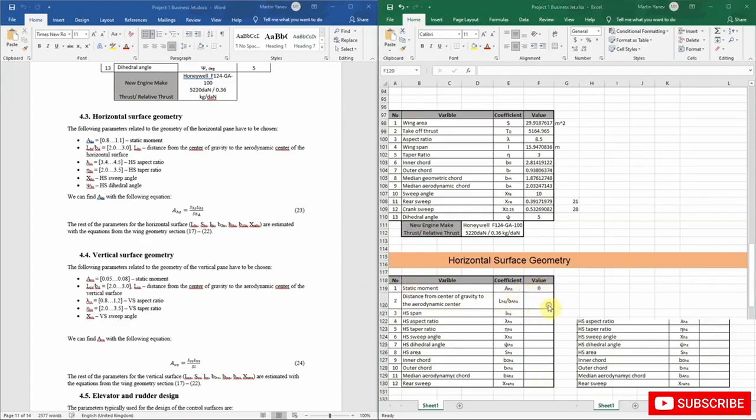So let's choose some of our variables according to what is proposed by other aircraft and by the studies completed for them. The LHS, which is the distance from the center of gravity to the aerodynamic center of the horizontal surface, divided by the median chord of our wing, should be between 2 and 3, so I will take it as 2.2.